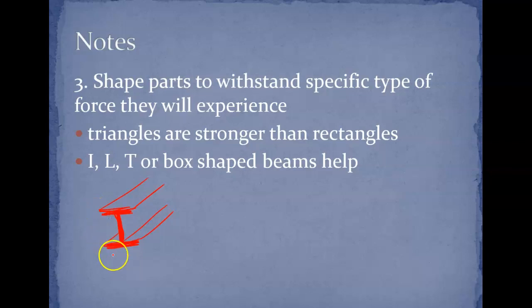The thing that happens here, as opposed to using a solid beam, is that this has less weight, thus less dead load. And we want to keep all the strength, so we maintain the strength with that vertical column, but reducing the weight or load acting underneath it caused by the size of the beam.